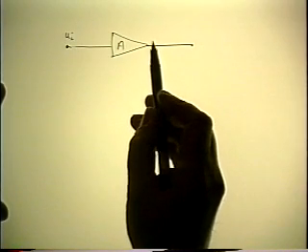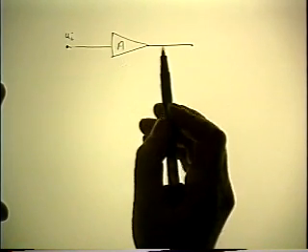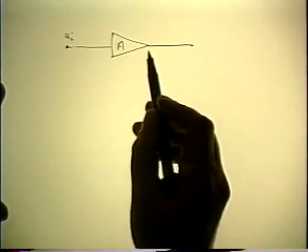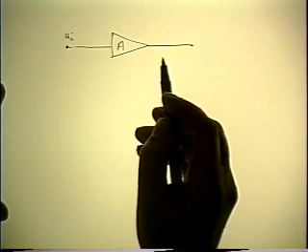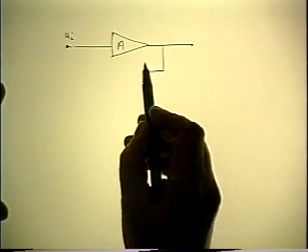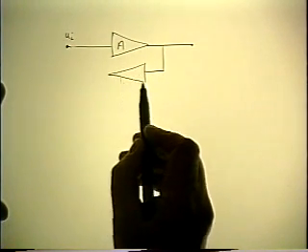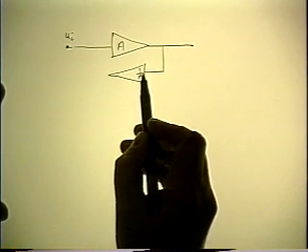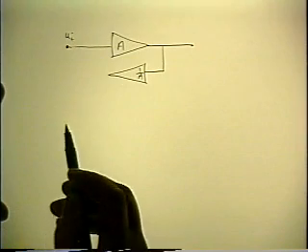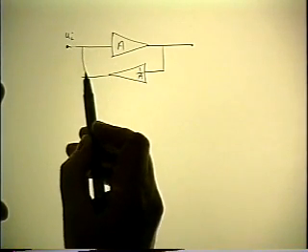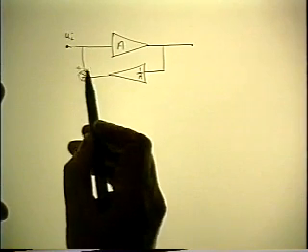And what comes out is an amplified fundamental plus harmonics coming from the nonlinearity or the distortion. So he says, let's take that output and we'll attenuate the output by the same factor that we just amplified it, 1 over A. Then let's subtract that from the original input.